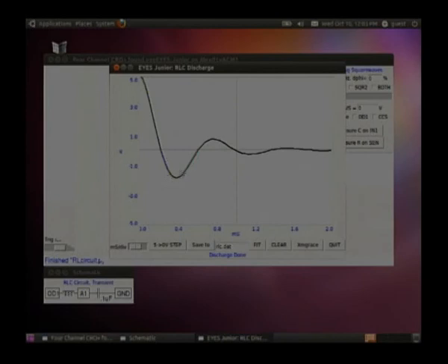Now, even though there are only a couple of cycles in these oscillations, we can find out the frequency. Press on this fit; it says the resonant frequency is 1.3 kilohertz and the damping factor is 0.309. In fact, you can verify this by comparing with the theoretical value, that is 1 by 2 pi square root of LC.